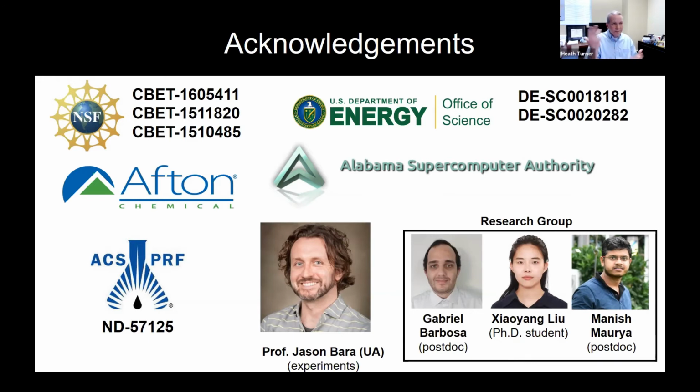If you have other types of membranes, you might get some blowout. And I'm just regurgitating some information that I get from some of my experimental colleagues, mainly Dr. Barry here, with some of the other applications where they've tried to incorporate some ionic liquids in other membrane platforms. If you go up to high partial pressures, those ionic liquids might over time end up blowing out or leaving, but in these ionic polyimides, they're very stable.